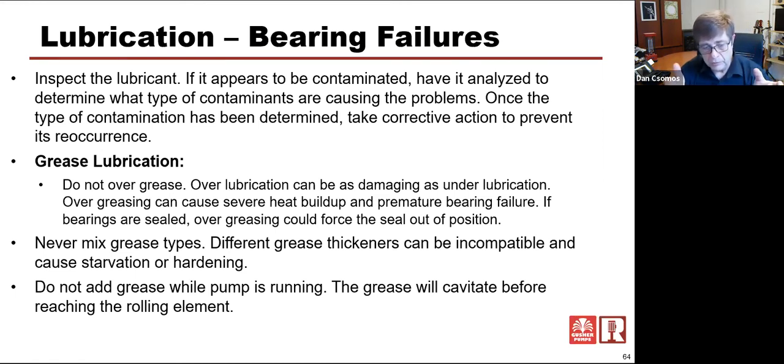The other type of lubrication is grease lubrication, and that may be a grease lubrication where you manually go out and pump grease into that bearing. You should pump grease into a bearing when it's shut off, not when it's running. Don't over grease, because if you over grease, the bearings won't roll when it starts back up. It'll try to push the grease out of the way, and the ball bearings will slide and scratch the race rather than roll on the race.